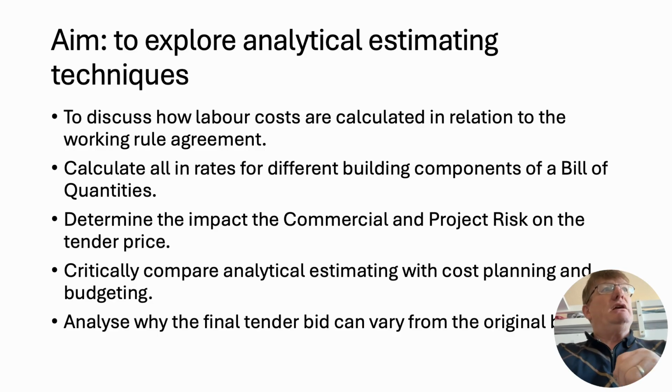You can start to base it on certain time and motion studies that have been carried out over the years, which are in various estimating books. What that means is you're analysing and breaking down the unit rate much more to a fundamental level. So you're converting, say, an hourly rate to a meters cubed rate or a meter squared rate based on current studies with regards to time and motion, and also current prices out there.